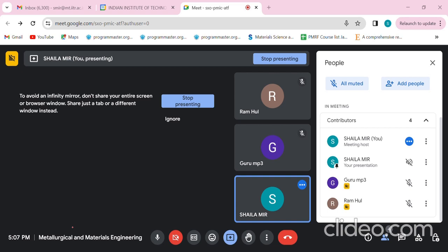You know that we have a Burgers vector, it has a magnitude, it has a direction, and the direction is in a particular direction. It is based on the slip plane, based on your atomic arrangements. There is a plane that slips with respect to the other. On that slip plane there occurs a dislocation, and that is given by a Burgers vector. For dislocations, we have two types, edge and screw. So you have to say what is the right option for this. How is the direction of a Burgers vector defined for a screw and edge dislocation? Can anybody answer?